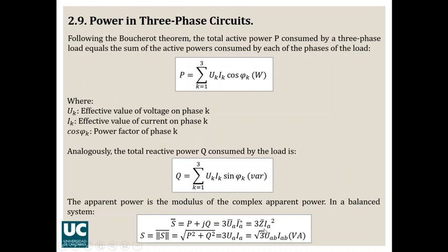So then you can transform this expression into this other expression, which is totally equivalent, which is 3 times the impedance multiplied by the absolute value of the current squared. Both expressions give a phasor, which is the complex power in voltamps. Obviously, if you want the apparent power, which is the absolute value of the complex power, you can do a